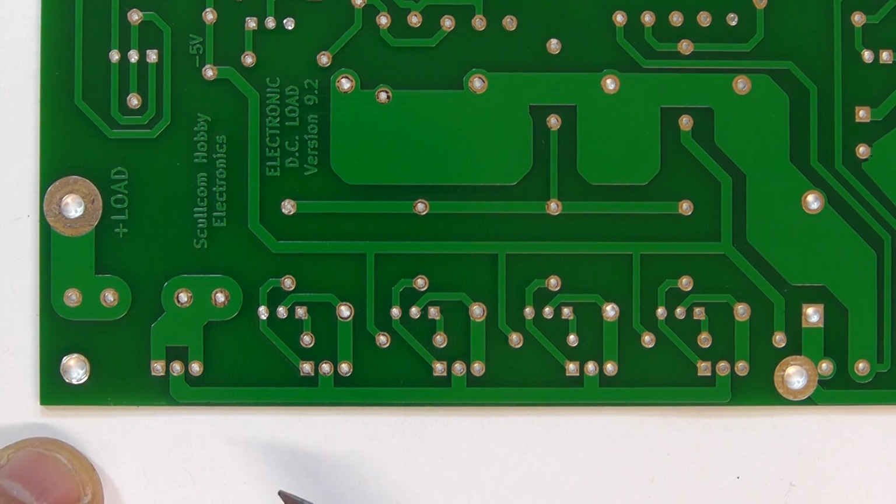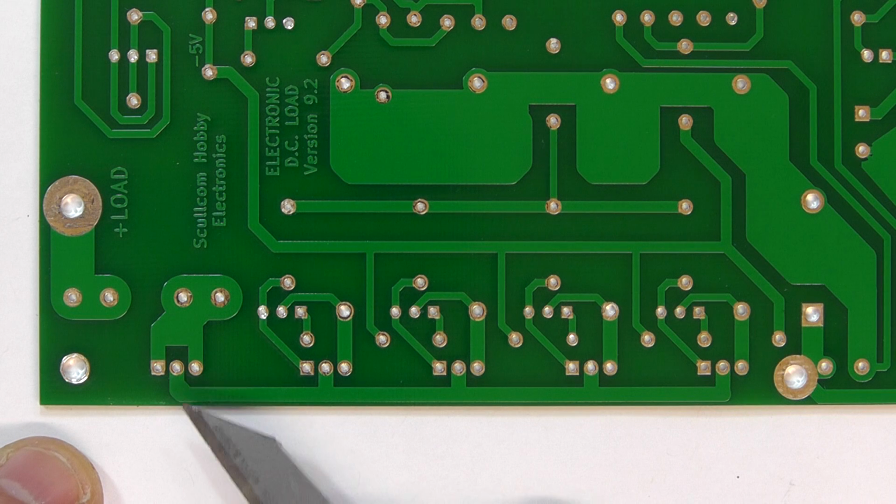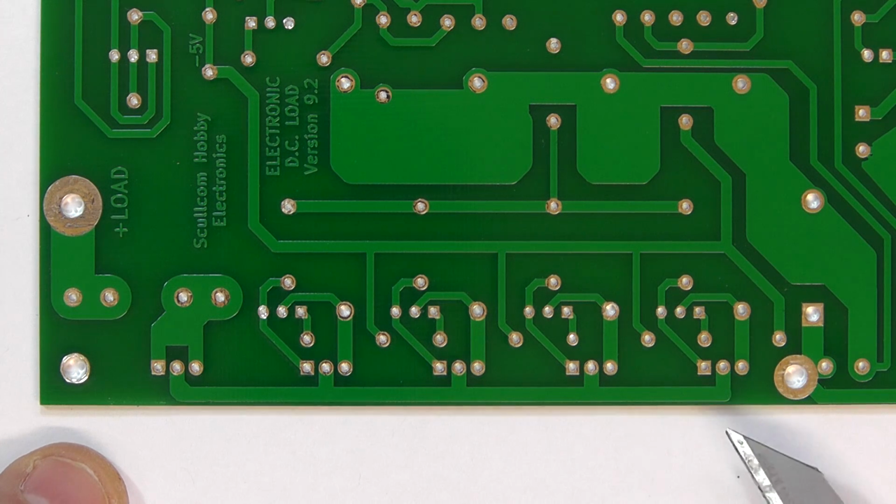Now another area of the PCB I'm going to make a slight improvement on is the area where we have connections to the drains of the 4 power MOSFETs and then to the dual Schottky diode there. Remember that we've now got the 4 power MOSFETs bolted to the heatsink with insulating mica washers, so they're no longer using the heatsink to connect the drains of the 4 MOSFETs, which we had previously. So we're relying on this track here on the PCB, and although I tried to mitigate the problems of current handling by adding an additional track on the other side of the PCB, it's still probably not sufficient at the higher currents, certainly up at 3 amps.